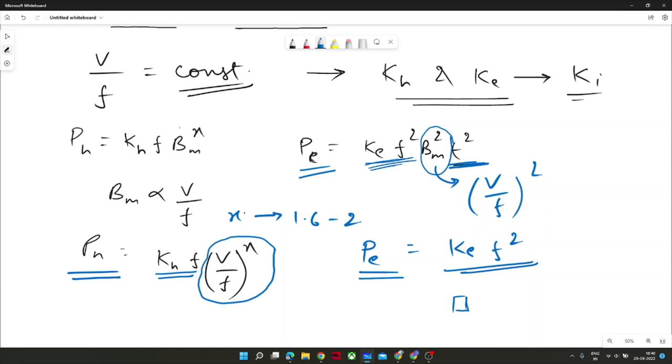Do you know how much lamination thickness we generally use for silicon steel in modern days? 1 mm, 2 mm? 0.2 mm? Yeah, you are quite close. Around 0.35 mm. Yeah, 0.35 is very common. That is known as material M235, or M19 as well. So 0.35 is very common. You can easily get it in India.